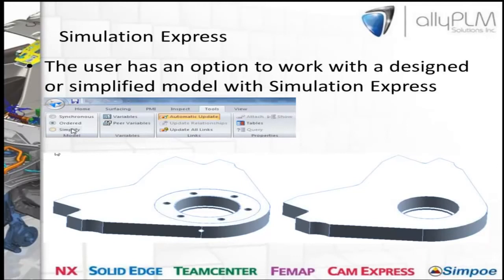Now at this point, I would like to bring up this idea of simplification. Usually what people do is they design a model, and they have a separate model for doing FEA. But with Simulation Express, as it's very well integrated inside Solid Edge, you can use your simplified models inside Simulation Express. In order to do simplification, you go to Tools, hit Simplify, and then you can use all your delete face and delete hole tools in order to get rid of some of the geometry which you want to eliminate. In this case, you'll see that this is my design body, and this is my simplified model, which I'm going to do analysis on.